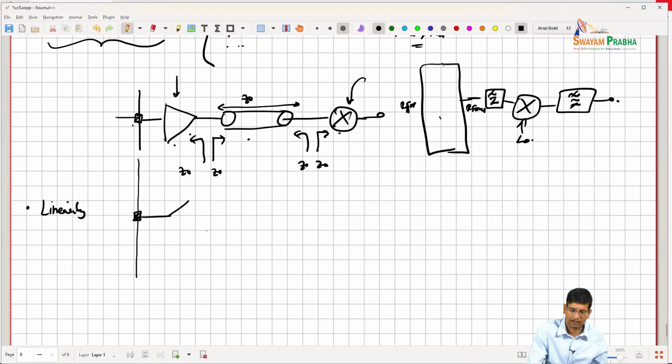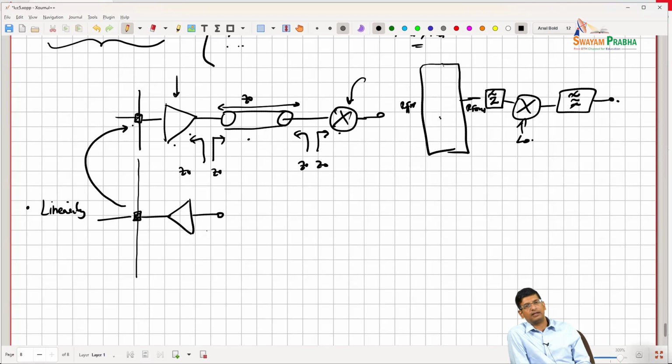Yeah, I mean, since we're not communicating, but effectively, if I have a TX leaking into my RX, this is a very strong signal, right? So then my LNA needs to be very linear. So if you look at millimeter wave radar systems, this LNA actually is very low gain and high noise figure because it needs to handle the strong signal. So that's the trade-off you made.